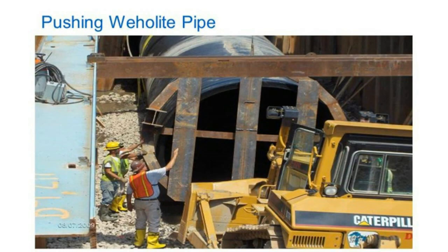So as you can see here, they lower the plate in. The plate is placed over the end of the pipe for protection of the end treatment, and before they begin pushing, they're able to advance the reline pipe into the host pipe by applying pressure to this steel plate or gate, if you would, that they've constructed without causing any damage to the end of the pipe.